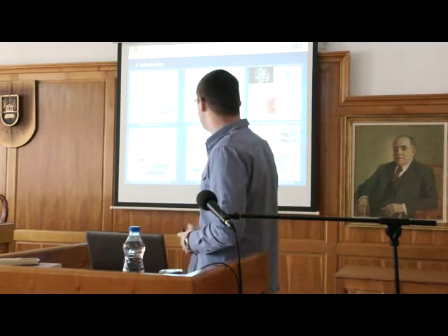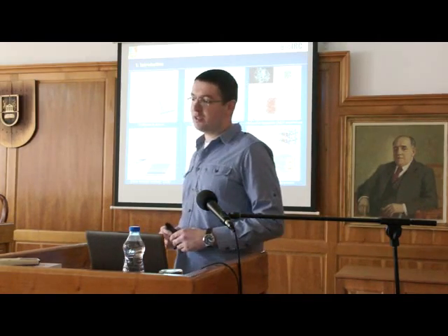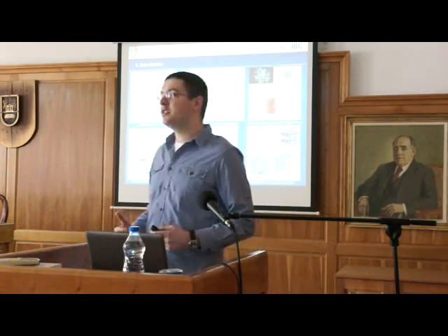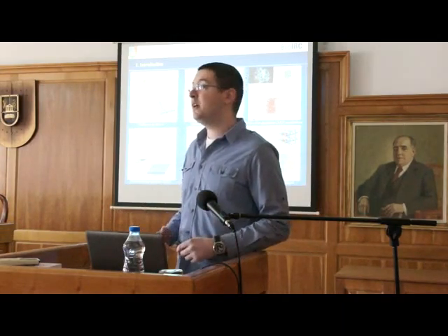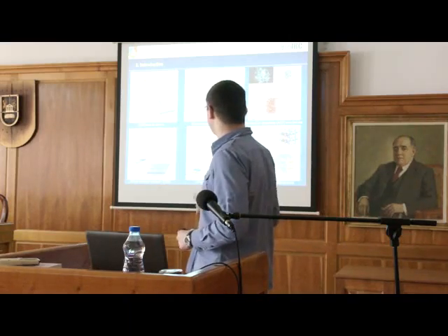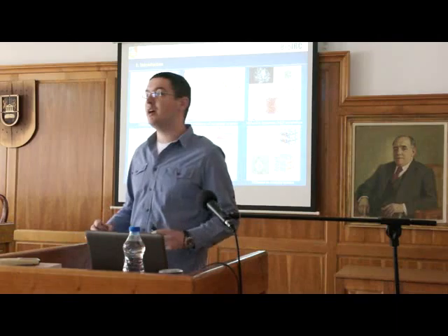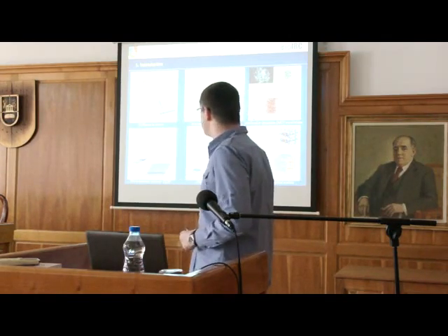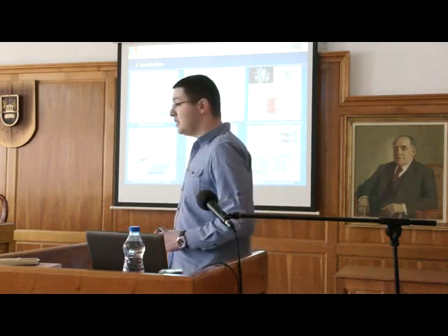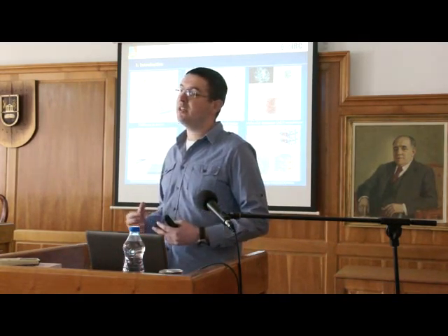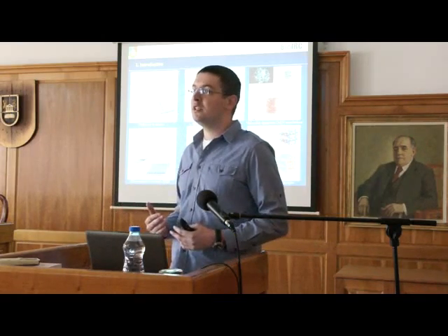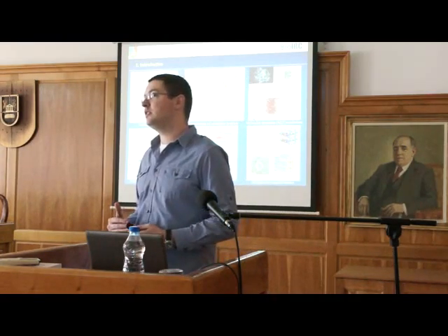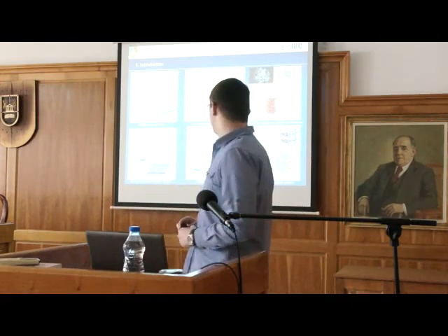Of course, we are dealing with the finite element method. Finite element method is a well-known continuum modeling method, but this method doesn't have these surface effects incorporated. One way to take these surface effects into account is to couple the finite element method and MD in a multi-scale method, and we developed this hierarchical model which couples FEM and MD in that way that we calculate these surface effects using MD, and then those scaling functions, which depend on the distance from the wall, we incorporate into FEM and do the calculation.